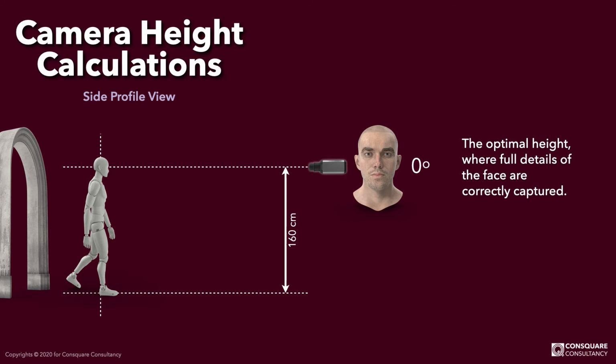Practically, putting the camera at this height of 1.6 meter from the finished floor level will expose the camera to many risks and the clear line of sight is not guaranteed. Therefore, we tend to raise the camera position above the horizontal line. The condition is to maintain the right view angle, to keep identifying the faces of the standard targeted individuals at high certainty.